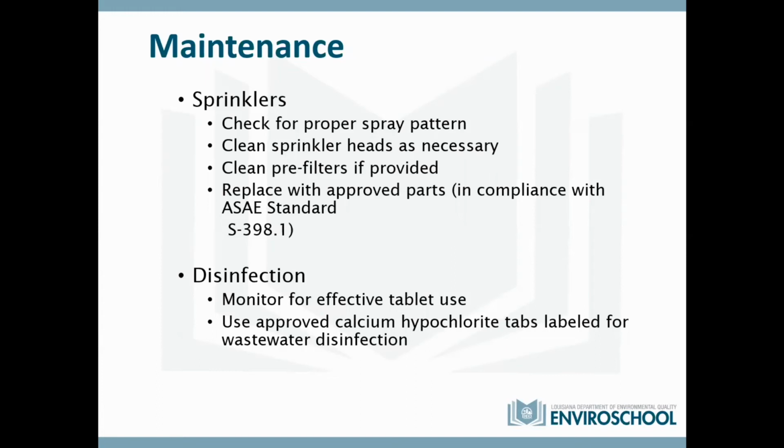This one says calcium hypochlorite tablets, but be sure they're specified for wastewater disinfection. When I did permits, I've been to inspections where you go look in the chlorinator unit, basically the chlorine chamber, and there are no tablets in it. That kind of stuff happens. You have to be sure you have enough tablets. Be sure and check it.